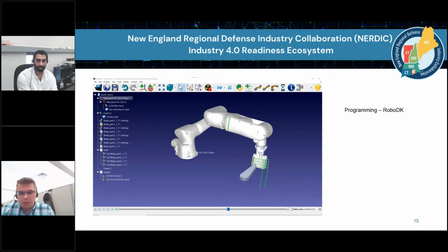Mastercam and any CAM program, really, for that matter, using their pathing algorithms to program robots very easily and quickly. Or if you don't need those, you can generate any program by selecting edges and paths in this RoboDK or similar environment to generate toolpaths in the virtual offline world, and then transfer them to your robot when the path is complete and you're happy with it.